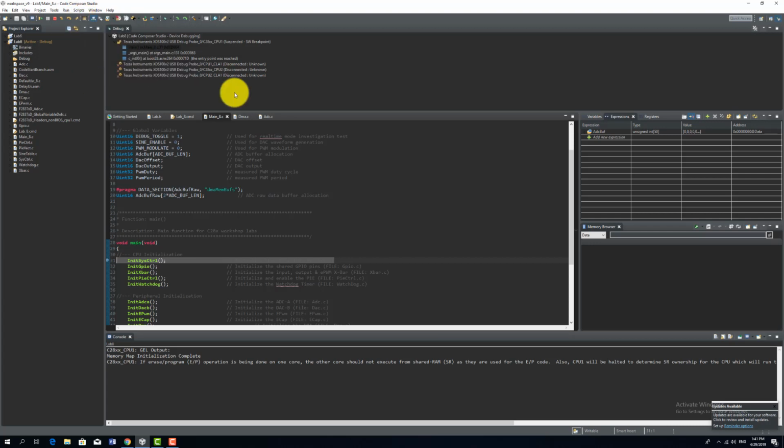And then the next thing we're going to do here is to get a value or signal from our PWM1A, and based on our developmental kit, the PWM1 belongs to J4. And then the signal will be coming from your pin number 30, which is ADCIN A0. So we have to connect these two using a jumper wire, pin number 30 and pin number 40. After we connect the wire, we are now ready to run.